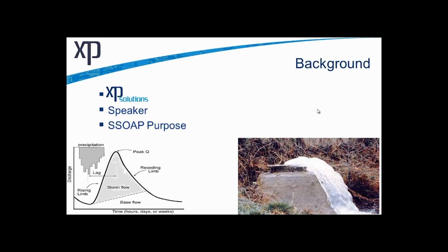So when there is rain in the system, the sanitary sewer system is not leak proof by any stretch. So that rain will enter the system to some extent. It may enter it in a very quick way through an illegal connection or through some structural failures, perhaps in a manhole. So you can have some very direct, quick inflow into the system. And it may enter in a slower, long-term way, infiltration by way of groundwater or cracks in pipes. There's different ways to characterize that, and there are different ways to go about trying to fix that or reduce it. And the toolbox is really built to help the user do that, to take real data, put it into the model, and develop some relatively quick output. And it actually will even allow you to run some scenarios to try to fix some of those results.